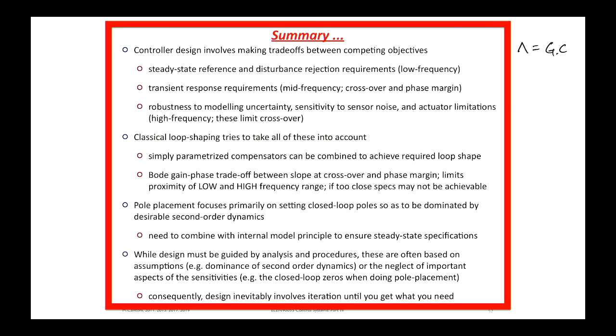And of course, what shape this has to have across frequency depends on what we're trying to achieve. But in general, we're trying to make sure that at low frequencies this has high gain, because that's consistent with getting small tracking error for low frequency reference signals. It's what's required to get low sensitivity of the output signal for low frequency output disturbances and input disturbances.